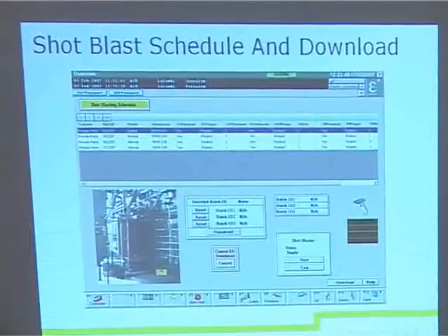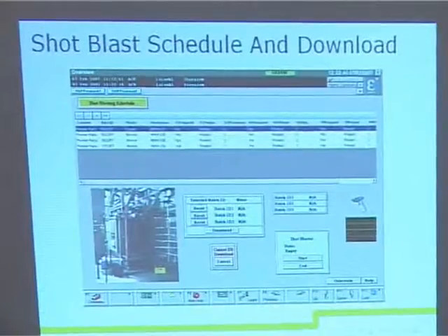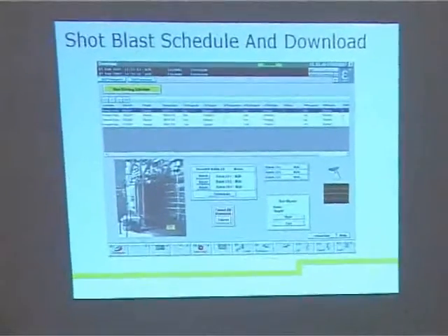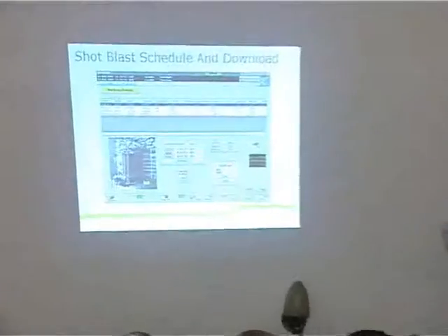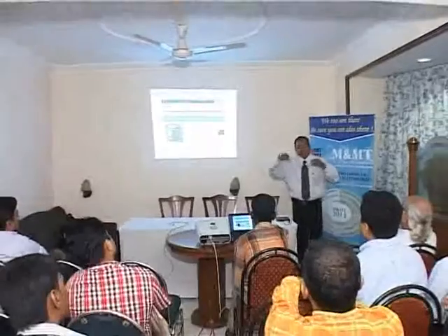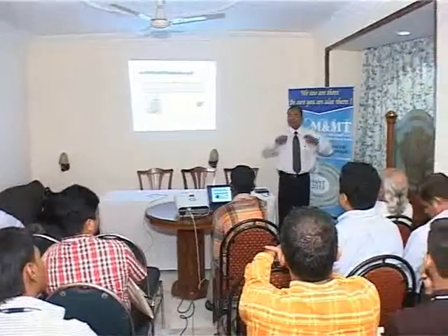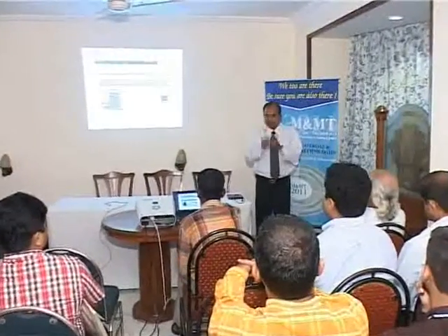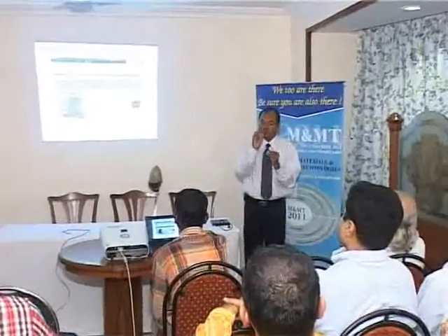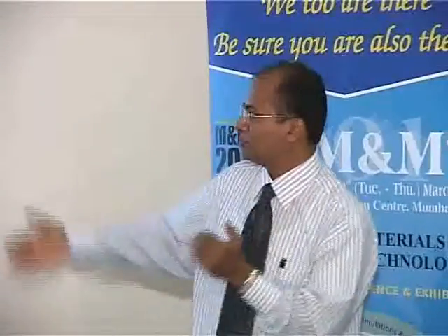So now what you do is, we initially go into the calibration of a furnace. So eventually you will possibly put 2 or 3 thermocouples, but initially you possibly put some 10, 12 thermocouples to see the uniformity of a furnace, to get into the optimal design of a furnace. Now for doing that, initially you have put those 10 thermocouples, but unless you have captured the data rightly and understood it rightly, only then will you be able to understand the location of those sensors. And for that, it is very much essential that you have the right data logging system in place beforehand at the time of designing. So that's what we can do.